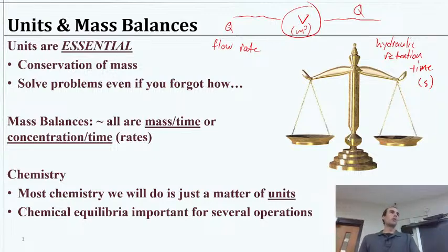We don't know the equation, so let's take a look at the units. We call this hydraulic retention time, theta, by the way. So theta will be some function of flow rate and volume. We just don't know yet. We know that it's going to be in seconds. And let's say our flow rate is in cubic meters per second. That's the volume of water per time.